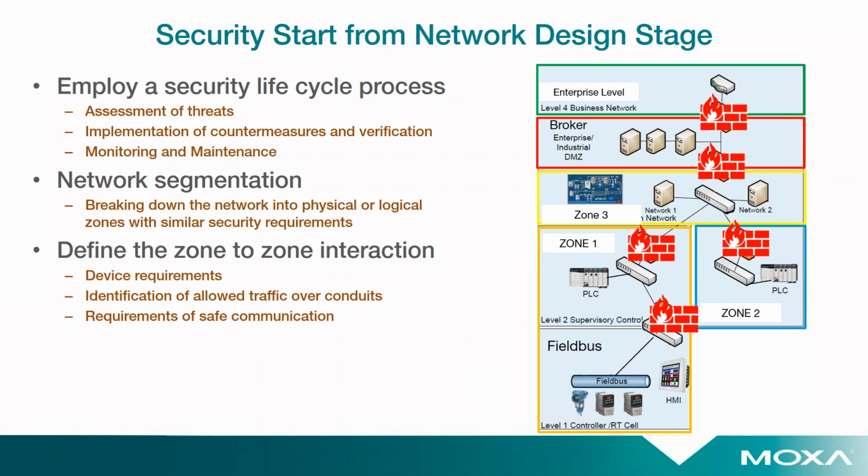So you need to apply conduits that can examine the different traffic. So maybe you have your enterprise level at the top in the green box there, and you want it to get the data so that they can process those dashboards to get the analytics, but you don't want it to talk to the SCADA to get that information. So you want to have a DMZ between it. You want to have something that can broker that information and also allow the SCADA to dump and process the information so that it can be accessible to your higher levels.